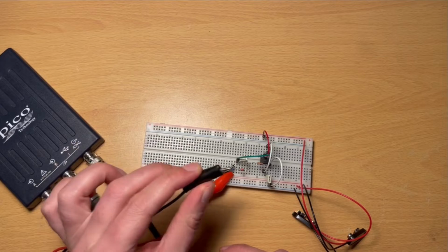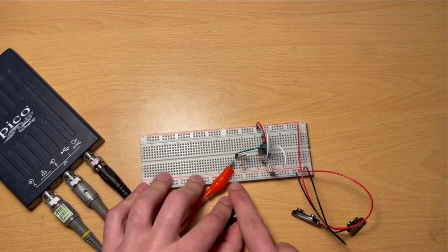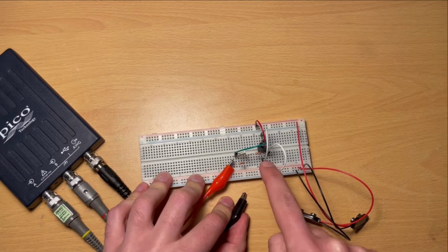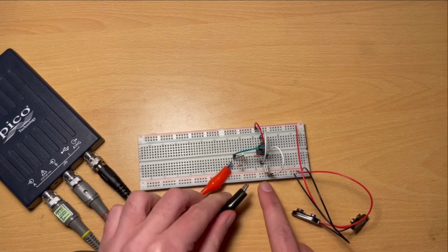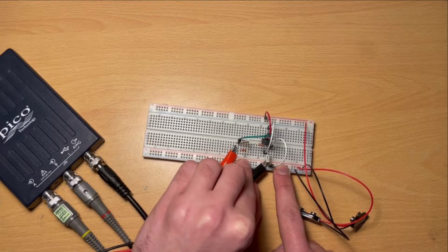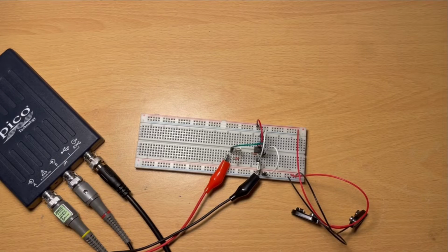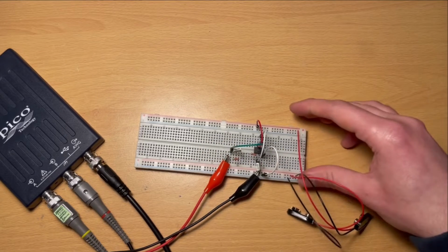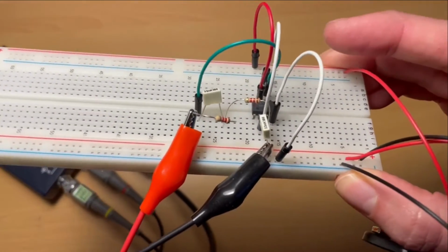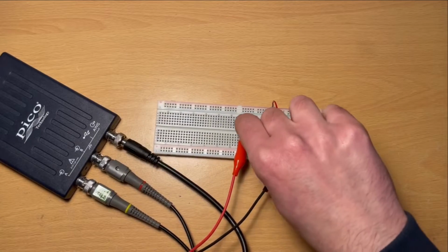Relative to ground, so the black connection here is going to ground. Now, what I've got here is a ground rail, which is the second bottom row. That's our 0-volt rail that we defined in the previous video. And I've only got one poor capacitor here that's going to have to be doing a lot of work in this video, I think. But I'm going to connect it to that capacitor leg there, because that's connected to the second bottom row in this circuit. Hopefully, if I bring it up a little bit closer, you may be able to see. Though I've just popped out a resistor there, so I'll stick him back in.